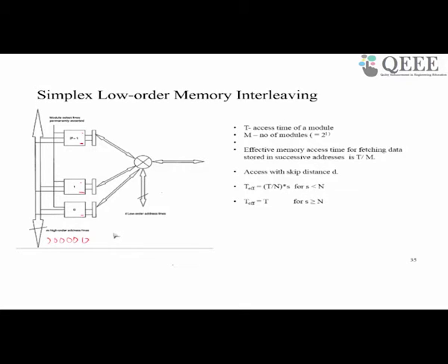After a time t, let us say t is the time it takes for the memory to fetch the content, the data will be available on the data port of all these memory modules simultaneously. Then we can latch it onto an output latch connected to these data ports.